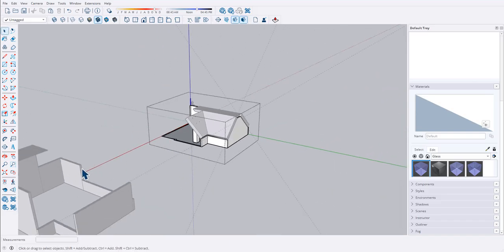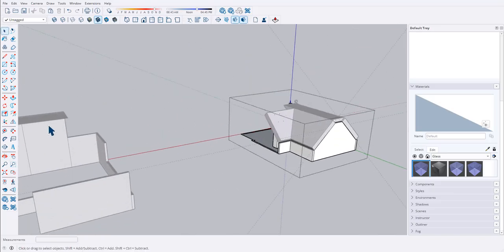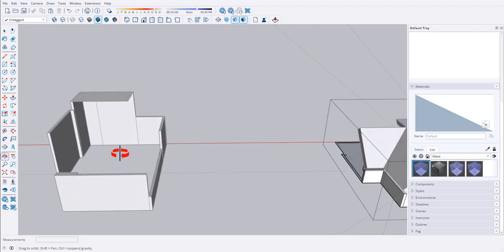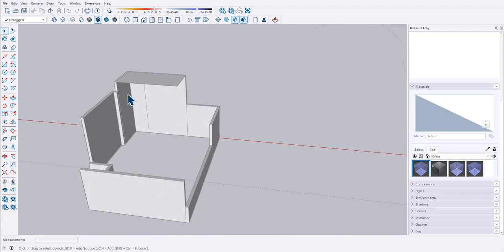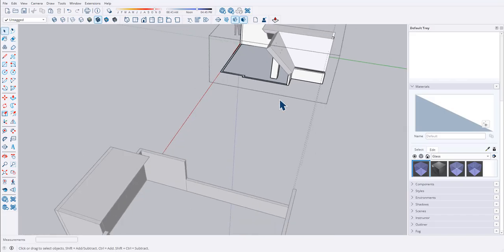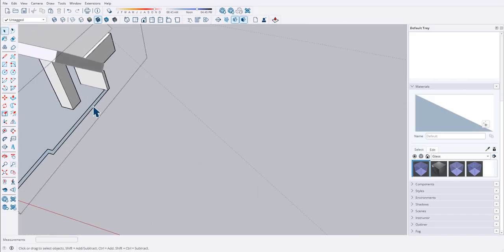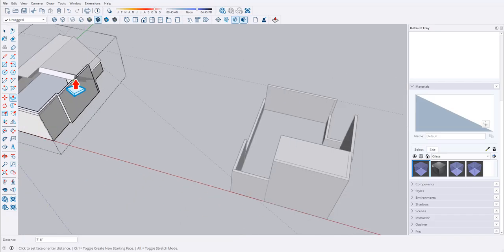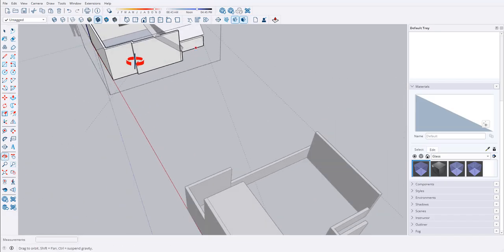So this does go up, because I can see that you've got a bigger height over here at the doorway area. And this is sloping, so I think I've got that pretty well set. This is going to be a sloping wall, so I'm double clicking here. P for push pull, and I'm just going to go up to at least this point on the wall.